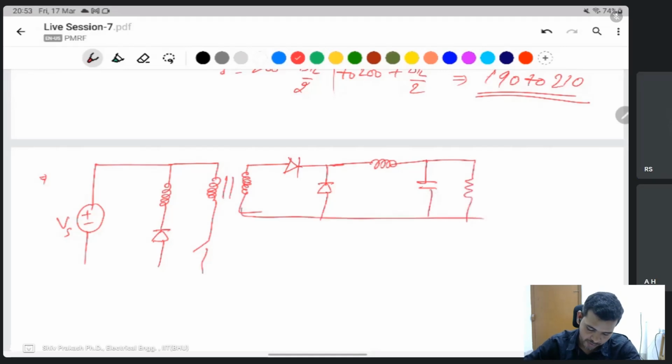So the simple forward converter. The magnetizing winding is a transformer. You can say the turn ratio is given for the magnetizing winding. The diode should be connected above the switch. The dot combination is the same for input and output, but in the tertiary winding it is opposite.